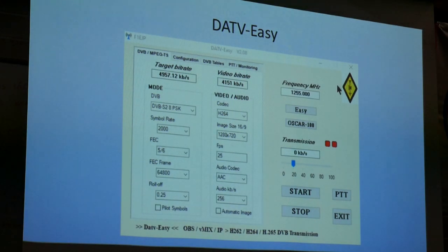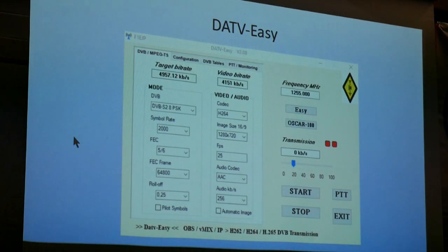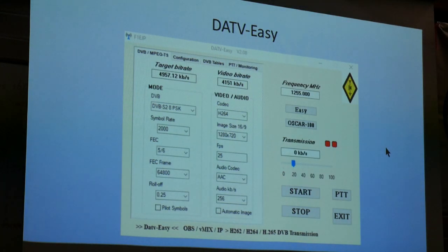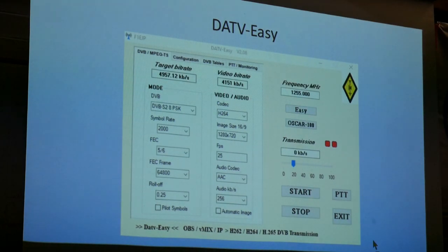Now on the output side of it, you do need an SDR. So it's the Lime SDR again, or it runs with a Pluto, and it does do the narrowband DVB-S modes, which is very useful. It doesn't do 7 megahertz wide DVB-T. It only goes up to 2 megahertz wide DVB-T. So if you transmit DVB-T with this, you're going to need a narrowband DVB-T receiver.